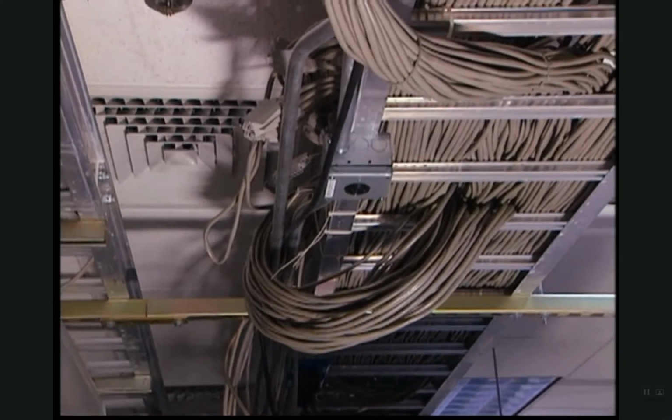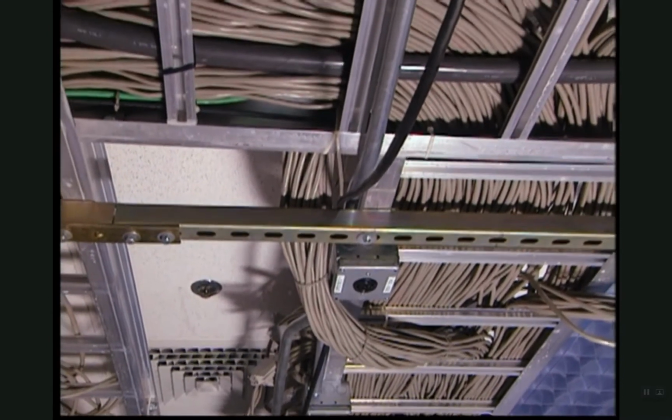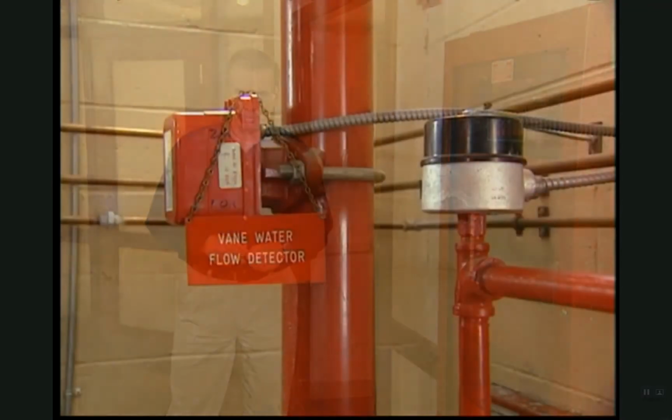A line-type heat detector senses temperature change anywhere along its entire length and is used in such locations as cable trays. Radiant energy detectors, also called flame detectors or spark ember detectors, are sensitive to radiant energy in the ultraviolet or infrared spectrums, or both. This type of initiating device is typically used in hazardous industrial settings.